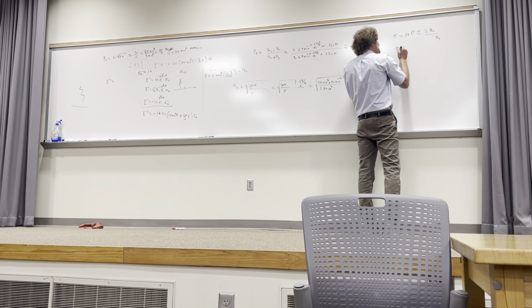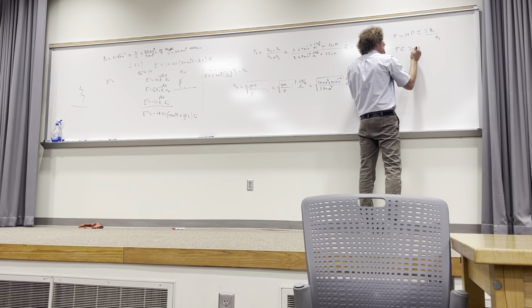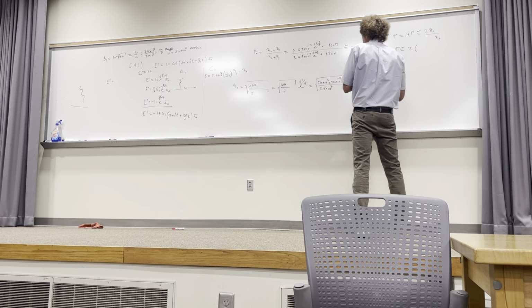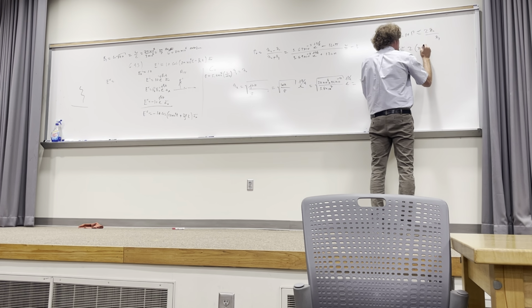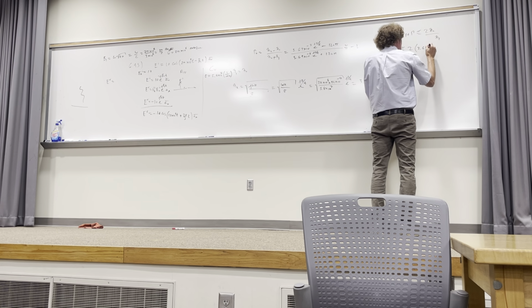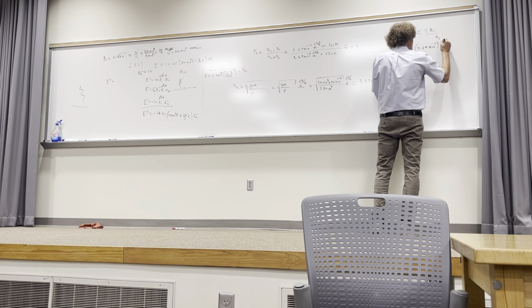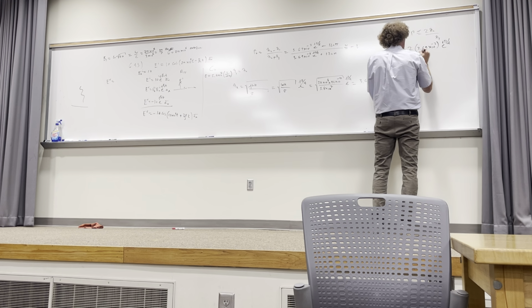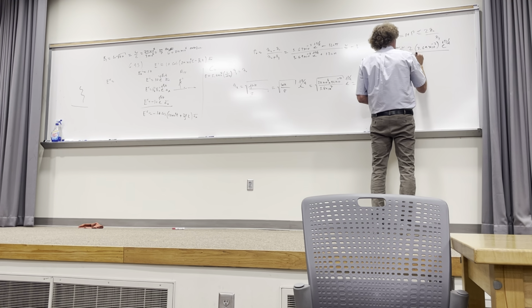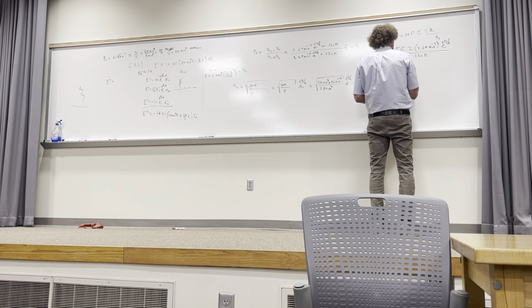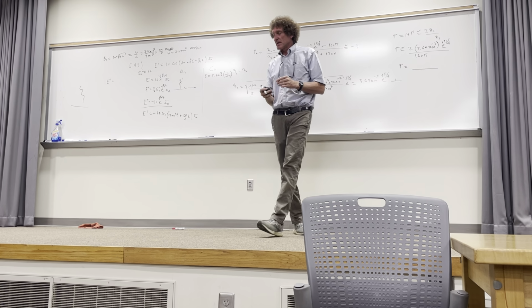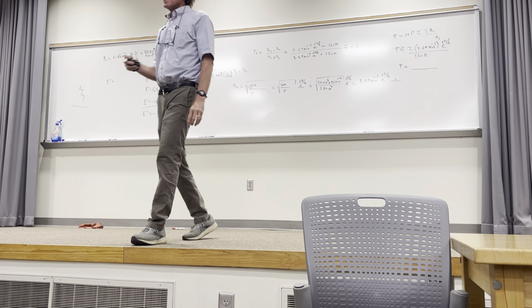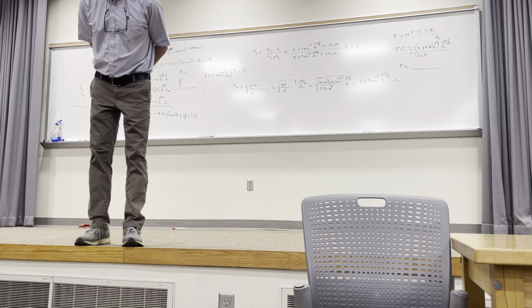That means the transmission coefficient is about 2 times eta 2, or times this, 3.69 times 10 to the minus 3 times e to the j pi over 4, over 120 pi. So you can give me that number, magnitude, and then just leave the e to the j pi over 4 there.